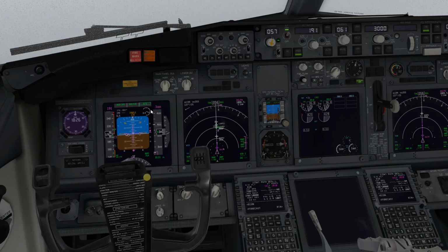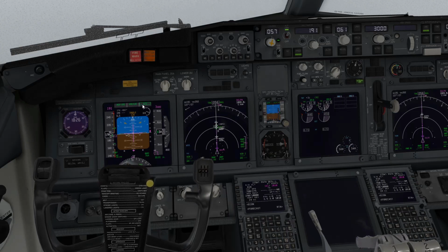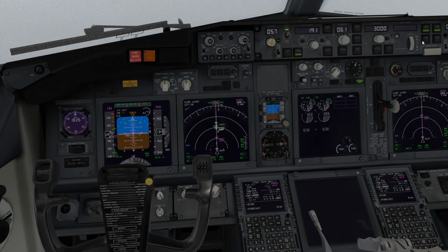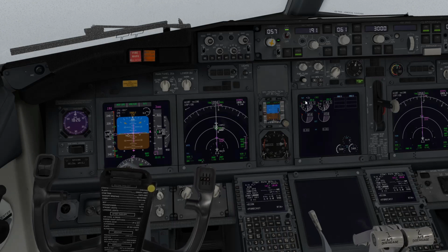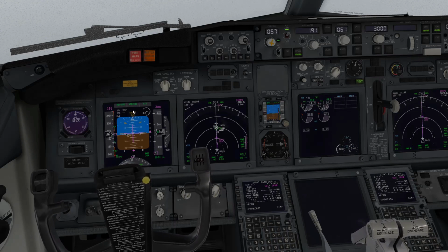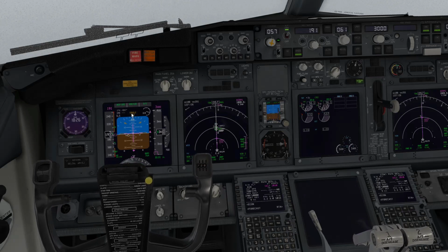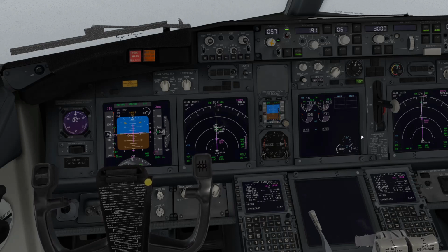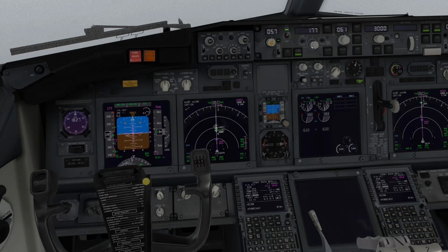And we've just hit the glide slope. We've got glide slope captured on the flight mode annunciator. We can now engage the second autopilot in command, and around 1,500 feet we should get a land 3 annunciation. It should come up in place of this single channel annunciation. I'll keep dialing the speed back to our flaps 5 maneuvering speed.